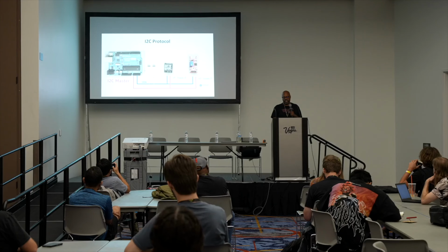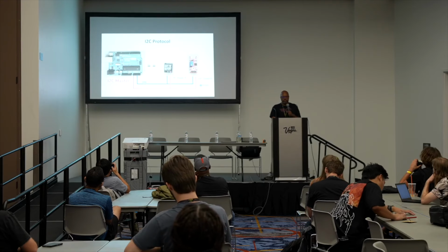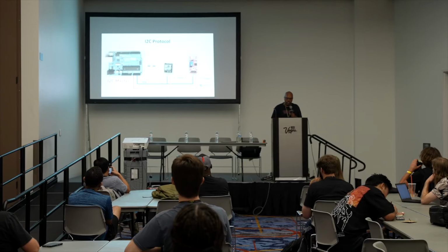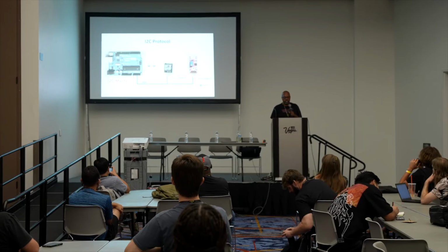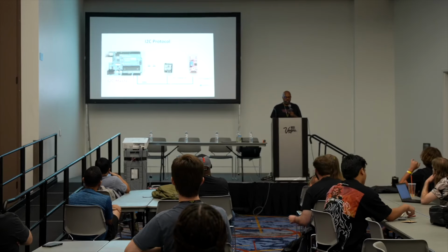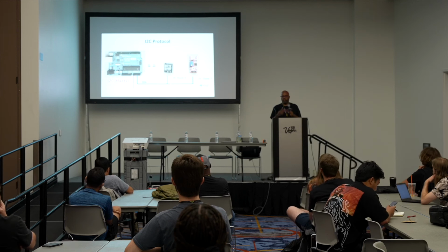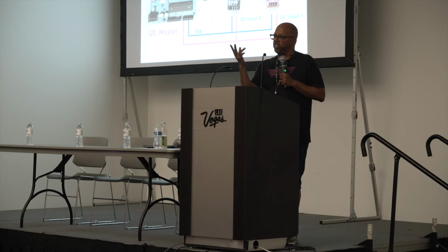And give you an example. Say I got, this is an Arduino actually, and I only connected to 2 components that I bought off of Adafruit or whatever, right? And these 2 components I know are I2C compatible. So when you look at the data sheet for these guys, it'll say, oh, this speaks I2C, this speaks I2C. So then you say, okay, I'm going to use I2C. So you wire it to the I2C pins of your Arduino. SDA and SCL are the 2 wires, 2 pins for I2C. SDA is a data line, and SCL is a clock, right?